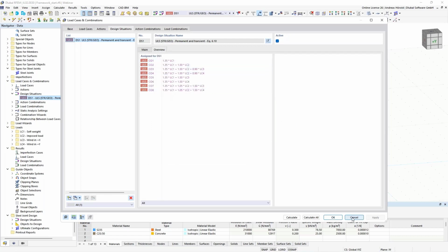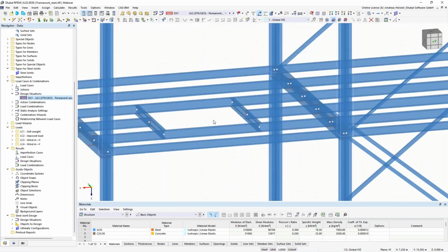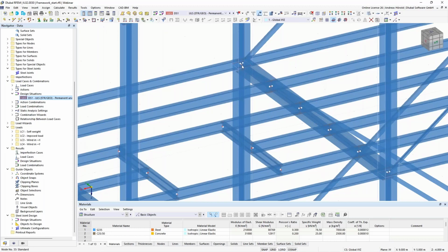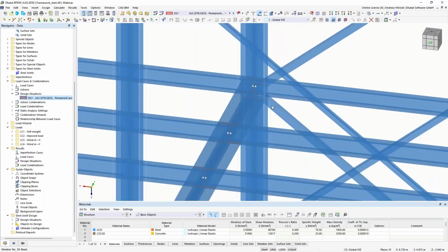So we can leave the dialog and start with the first steel joint. Maybe I can show you that in the model. I would like to use this node here, and I will define all connections for that node: the rigid connection of the steel frame, the pin connections of the platform beams, and the two connections for the bracings. Those are L sections.